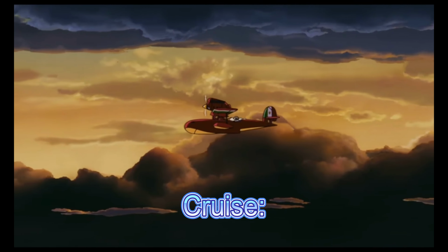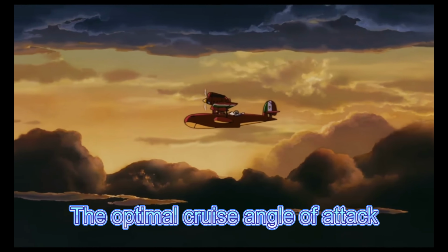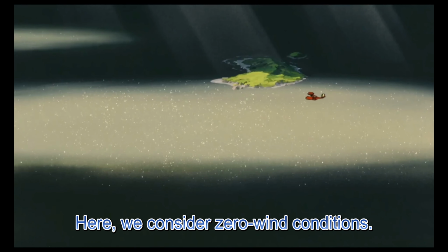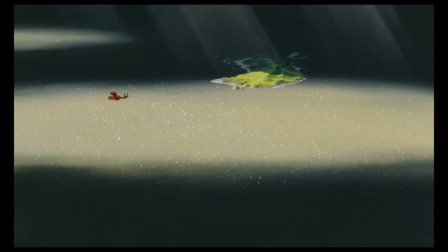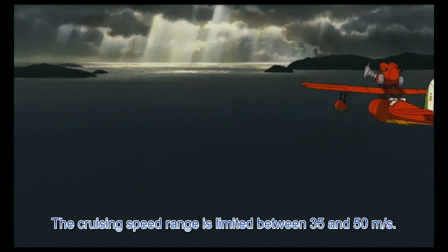In the cruise phase, the main objective is to calculate the appropriate angle of attack for steady flight without considering natural wind effects. By applying the balance equations, we can compute the corresponding flight speed and the required thrust at different angles of attack. Taking into account energy losses during flight, the cruise speed range is limited between 35 meters per second and 50 meters per second.